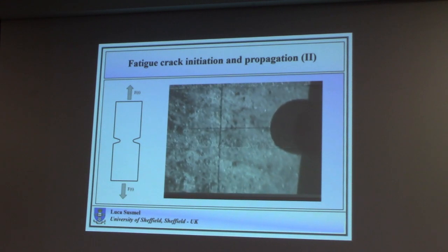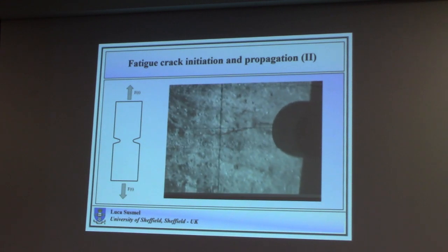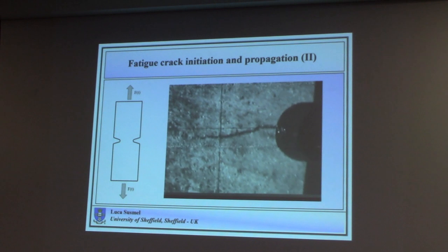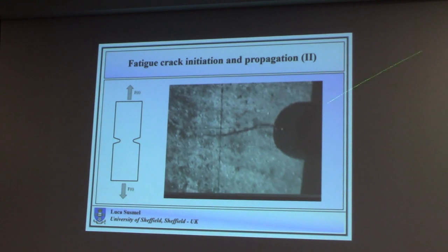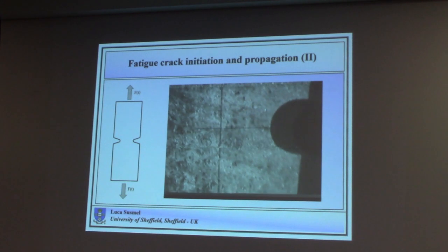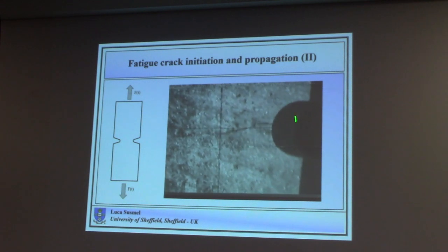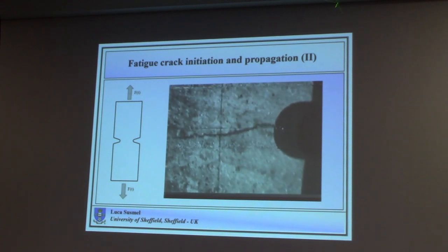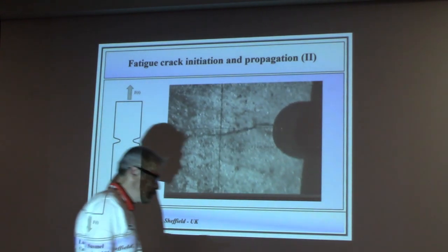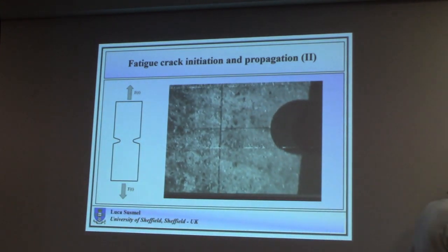But now you can do the local stress analysis, and what would you expect to have here at the center of this plate? A kind of triaxial state of stress, or at least more triaxial than the stress you have on the surface. So physically, what the material feels is locally this state of stress which is more triaxial than the one you have on the surface. So you end up having your crack initiation happening at the midsection here of the plate. Okay? So, hopefully I'm trying to deliver the big message. And please keep it in mind over the next 2 days.